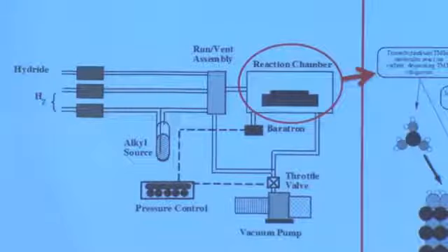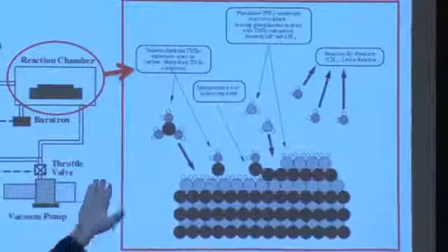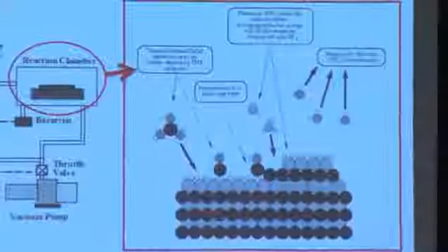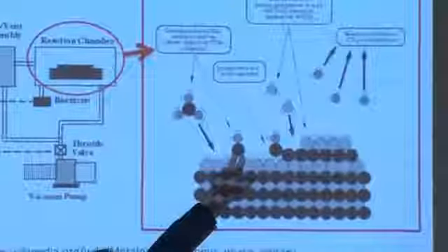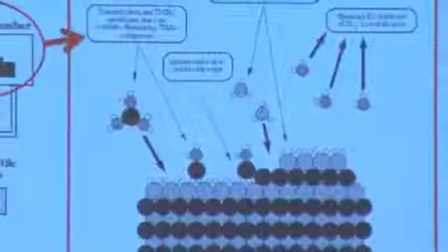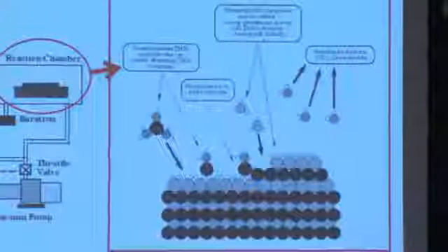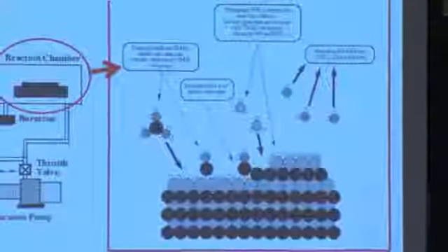That is represented chemically here on the surface. This is zooming in right at the surface of our sample, so right where the gas interacts with the thin film material that you're depositing. This is representing the incoming metal-organic molecule, right, reaching the surface. This represents right here the separation, where we have the indium atom shown in black right here. And then the methyl groups are moving off, and essentially those will be sucked out of the chamber, leaving behind, in this particular case, a layer of indium forming, probably another layer of material underneath, say, for example, your other species comprising the thin film, maybe phosphorus, so it would be indium phosphide growth.